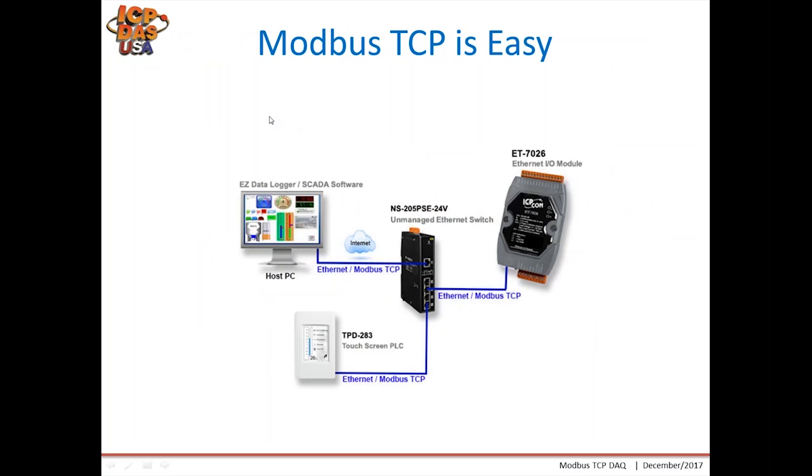Modbus TCP is very easy as well. It's very easy to implement. You just simply use an Ethernet switch, or you can even plug a data acquisition module directly into an Ethernet port.